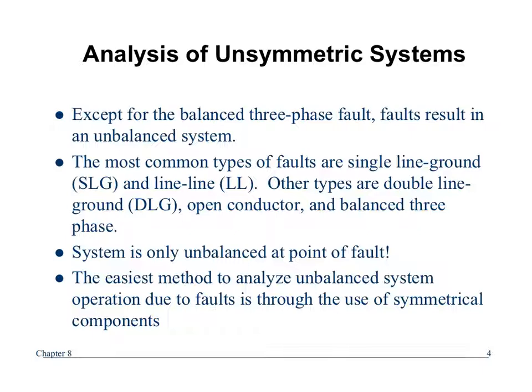When I think of fault currents, right, what do you typically think of? Got a 3-phase fault or a single line to ground fault? I got to respond to that, right? And I got to protect my equipment from those big fault currents. But there's also a concept of what's called reach. What if the fault is not one of those two faults, but it is a line to line or double line to ground fault?